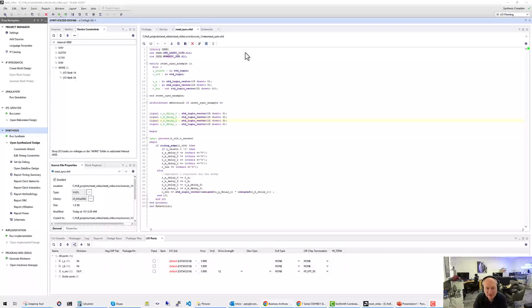Okay, we've created a project which is just targeting any AMD 7 Series, UltraScale+, or Versal family devices, and we've created a simple bit of code here. This one's doing a synchronous reset on a multiplication between two numbers. As you can see before, we're providing the two delay stages. And the crucial part here is in the reset element. The reset element is occurring on the rising edge of the clock, making it a synchronous reset. And then if the reset's not active, we're running through and doing a multiplication and popping the data out.